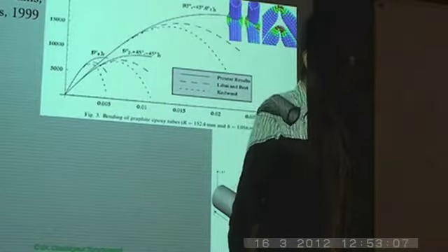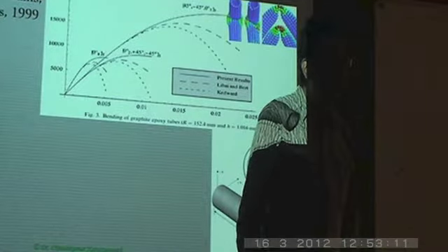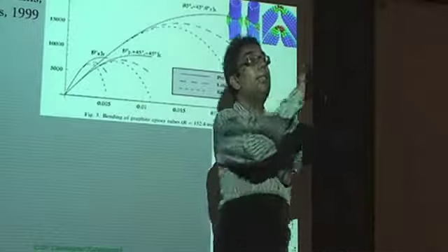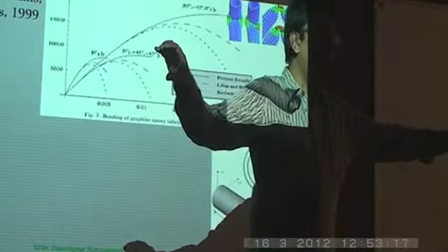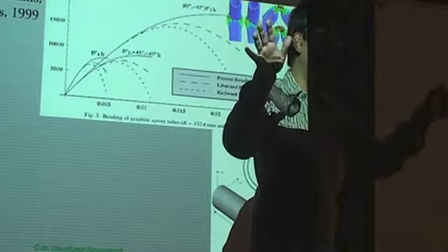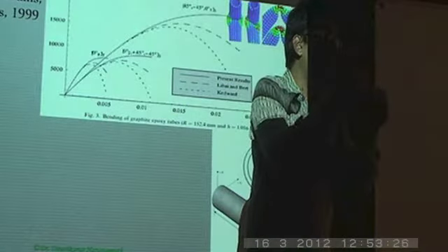Yeah, actually I have one doubt. How do you differentiate between local buckling and this kink formation? See, the local buckling is a global phenomenon in the sense that it is a 1D phenomena. Okay, so it's basically a relationship between your bending moment and curvature, assuming that none of these local problems happen.